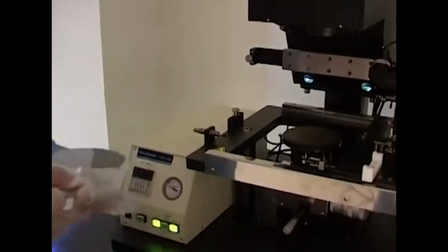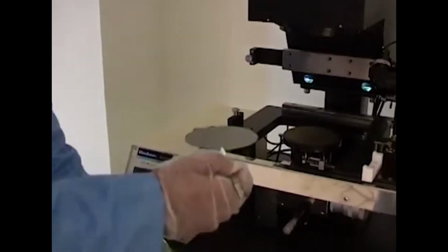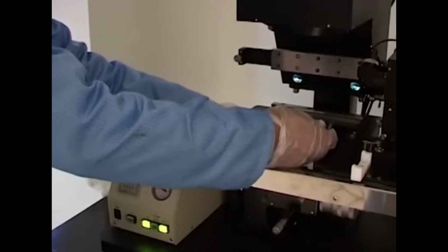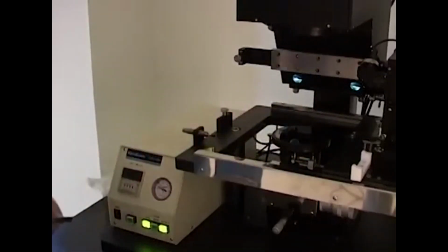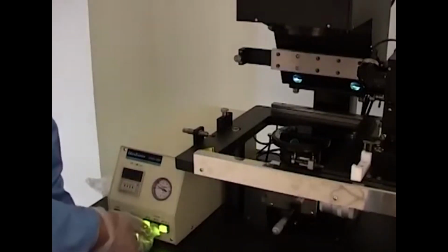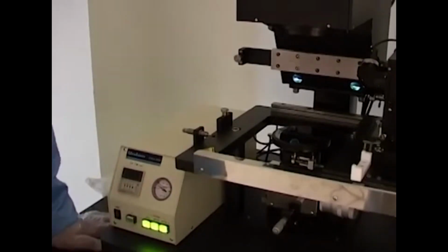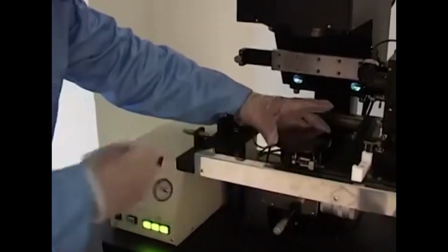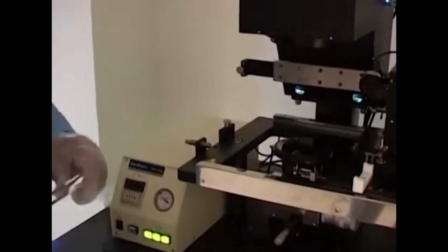So essentially now we are going to take the wafer from its box and put it in this particular zone here, which is meant for wafer holding. Okay, again we would like to use vacuum as a means of locking this wafer, the spun coated, resist coated wafer, onto the exposure stage. And this switch right here, which says wafer vacuum, ensures that the vacuum is used to pull and lock the wafer. I want to check whether the vacuum is working well, and I found out that it doesn't move anymore. The wafer is jammed with respect to the stage.